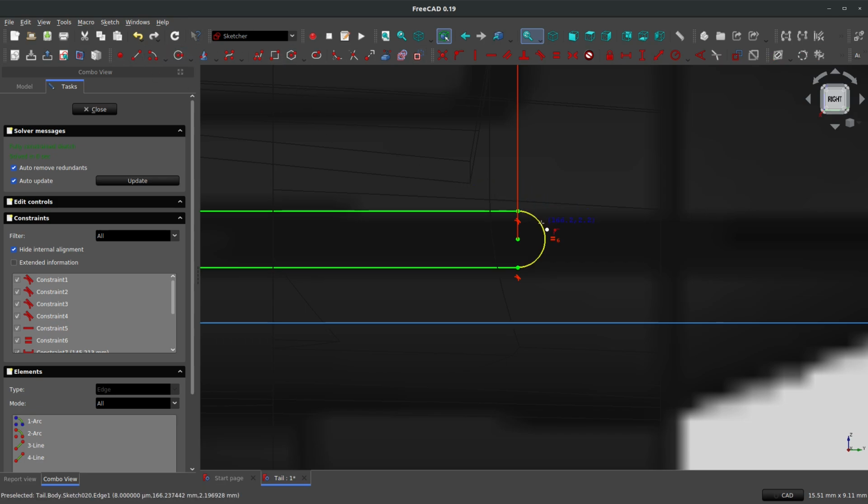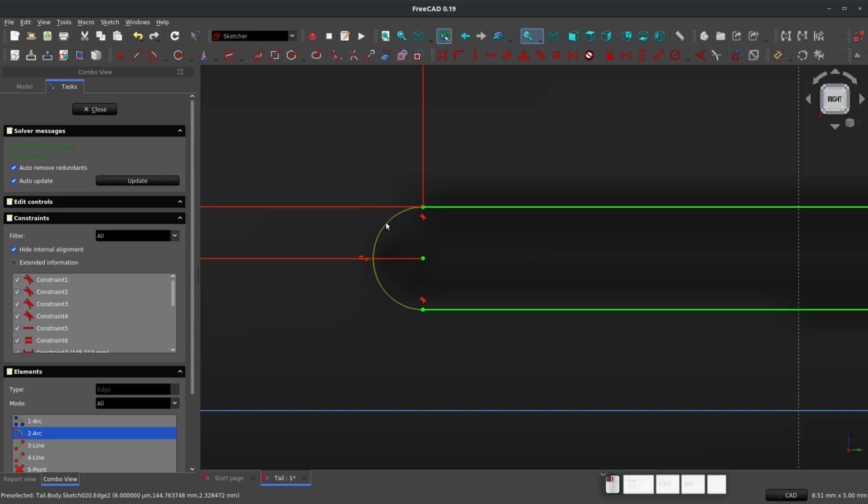I'll add a point coincident onto this arc body, and we'll go with a horizontal. In fact, I think this is my first time using hotkeys, so I'll bring up my keyboard monitor in case you need to see what keys that I use, but I'll make this horizontal. We'll do the same up here for construction, and we'll add in a horizontal point horizontal, and I'm going to grab an arc. You certainly can use a center point arc if you like.